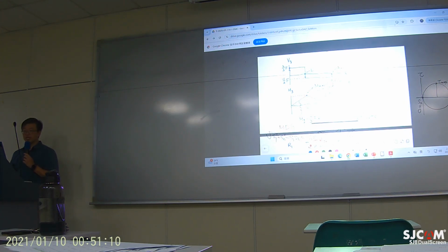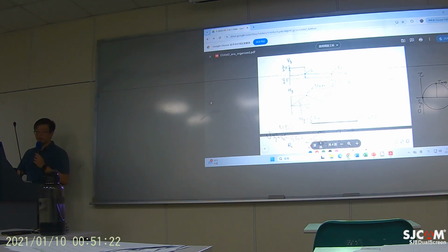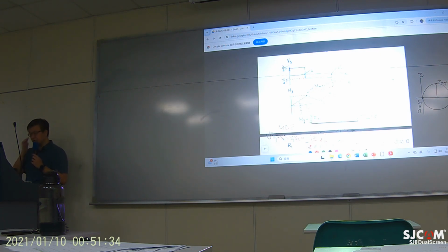And you can very easily get the linear equation of the first portion, where the slope is going to be 2/3 of F multiplying the distance. And then you can plug in the position L, where you obviously see there is a peak of the bending moment. So you plug in L, then you get the largest moment equal to 2/3 of F times L. So that's the largest value.